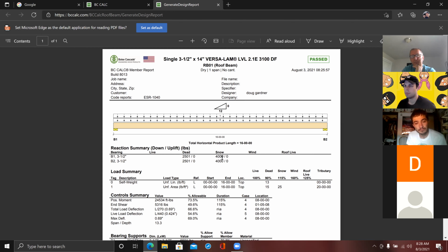And so when they break them, if they advertise that a beam's going to hold 100 pounds, does it make sense they better design some safety into that and it better hold more than 100 pounds? Turns out the right answer to that question when they test it is about double. In other words, these are double as strong as they're advertising them to be. So if it says 99%, I'm not like, ooh, that's close, it's going to break. I don't even care. If it's 99%, I'm fine, because it's twice as strong. Not only that, when it fails, it's not like the whole thing falls down. It just bends a little too much. You see what I'm saying? So there's a safety factor built into this.